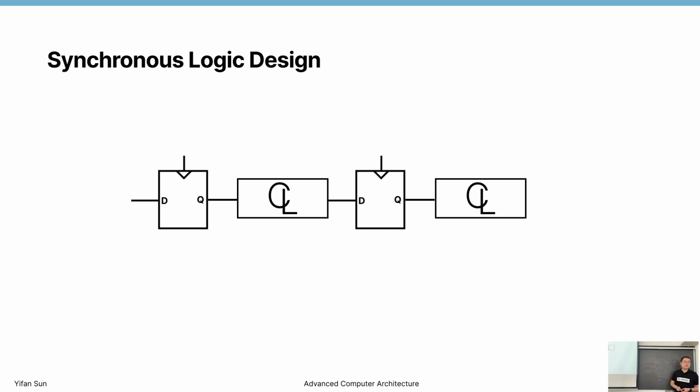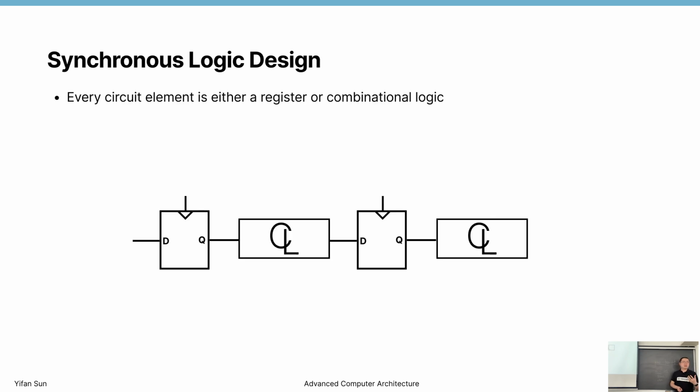If you need more than 8 levels of gates, you have to split it into a multi-cycle operation. You cannot do that many things within one cycle. That's why you probably heard in CPU cores, at the beginning there was a 5-stage pipeline. Later on, it was extended to more than 20 pipeline stages. Why do they do that?